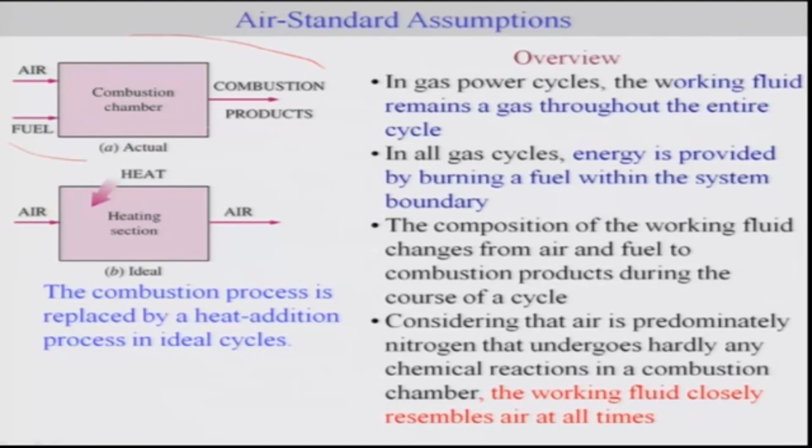As I said, air plus fuel combustion goes to combustion products, and there is heating. This can be idealized in the form that you have simply air, and whatever energy is generated can be represented as the energy being provided to the heating section, leading to air. So considering the air is predominantly nitrogen, which undergoes hardly any chemical reaction in a combustion chamber, the working fluid which we are going to consider closely resembles air at all times.